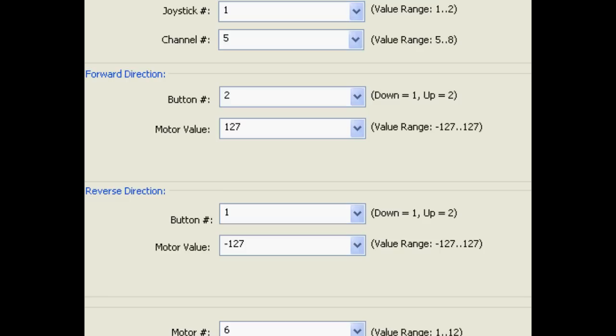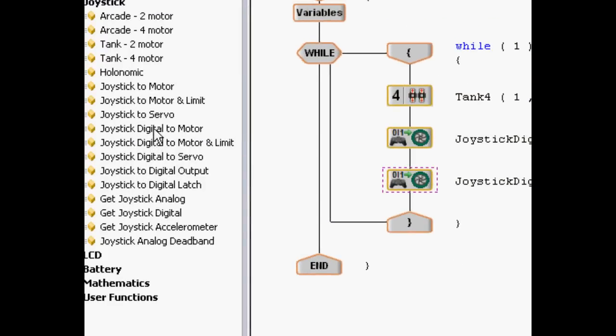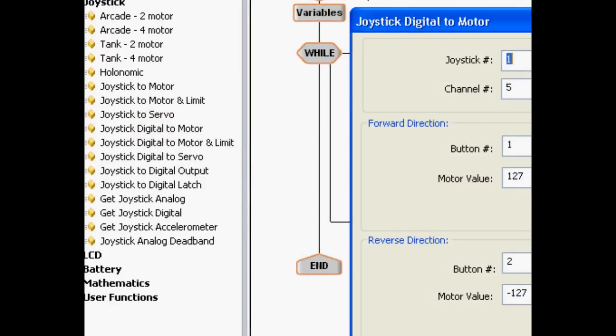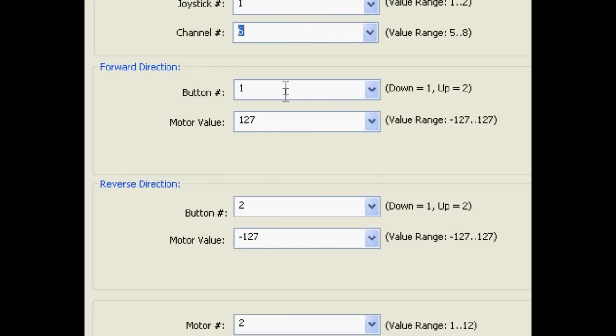Like I said before, you'll want to do some testing for this to make sure that you have the right motor inverted. Now the gripper is the exact same thing as the arm, so program the gripper the exact same way, except put in the motor ports that your gripper motors are plugged into, and change the channel to another channel of your choice.